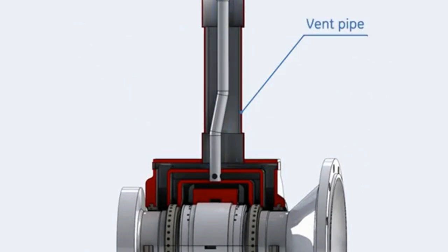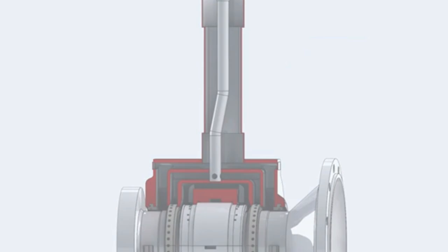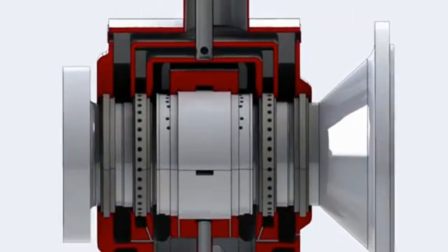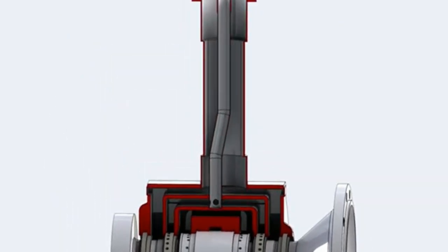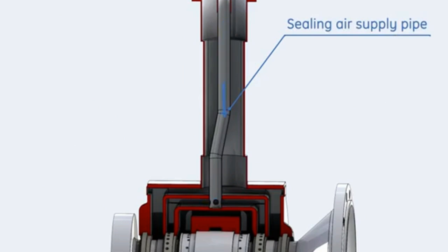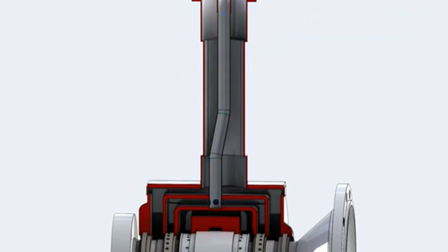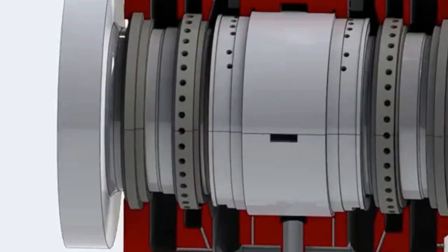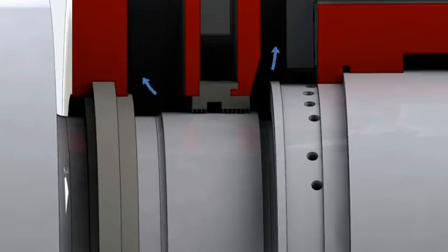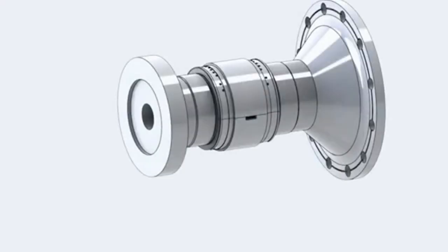Inboard of the outer air seals, two pressurized labyrinth seals are located for lubricant control. Sealing air supplied through a pipe concentric with the vent pipe fills the sealing air cavity and flows between the two rows of each of the labyrinth seals. Some air escapes to the vented cavity, and the remaining returns with the lube oil. The journal bearing components are the bearing liner and the journal surface machined on the turbine forward wheel shaft.